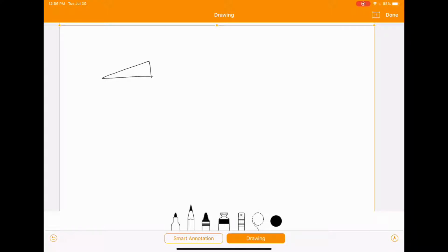are a slope distance and an elevation difference. And again, they want you to find your horizontal distance. So there's a couple different things you can do for this. The first method that you can use is our alignment correction that we learned in the previous video. Or you can use Pythagorean theorem.